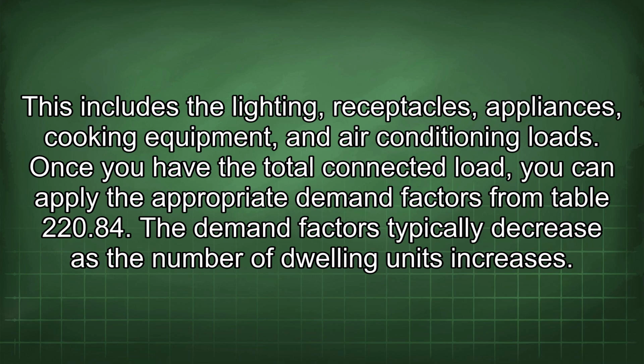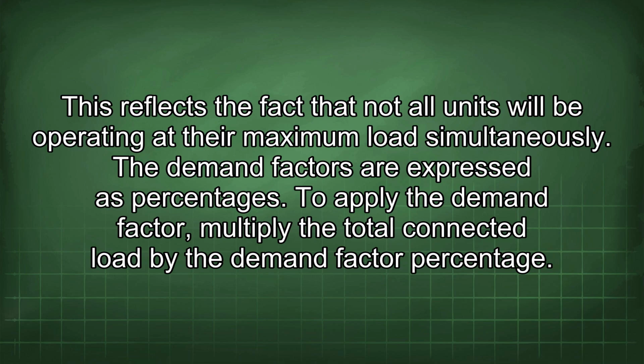The demand factors typically decrease as the number of dwelling units increases. This reflects the fact that not all units will be operating at their maximum load simultaneously. The demand factors are expressed as percentages.